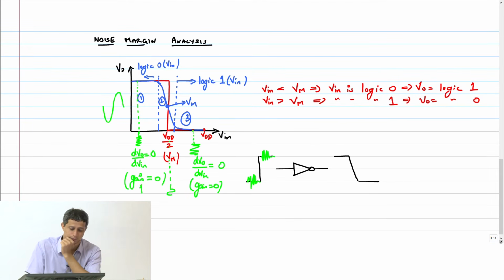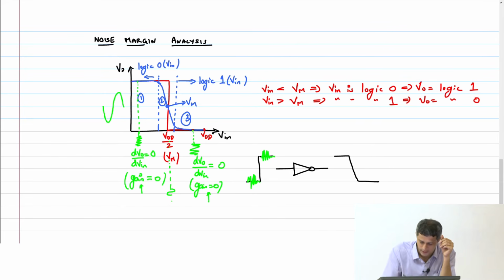Here gain is 0, here gain is 0, here gain is very high and it is a negative number. Okay, mod gain is actually much greater than 0. So what do you think should be this magic transition value for the gain for me to determine these regions? Noise should not get amplified. That means the point at which the gain actually hits -1 is the point to the left